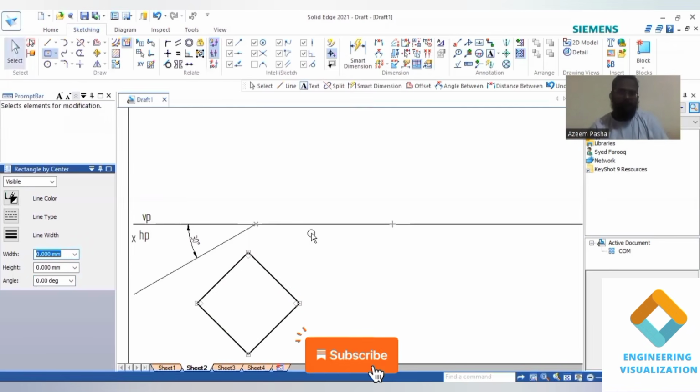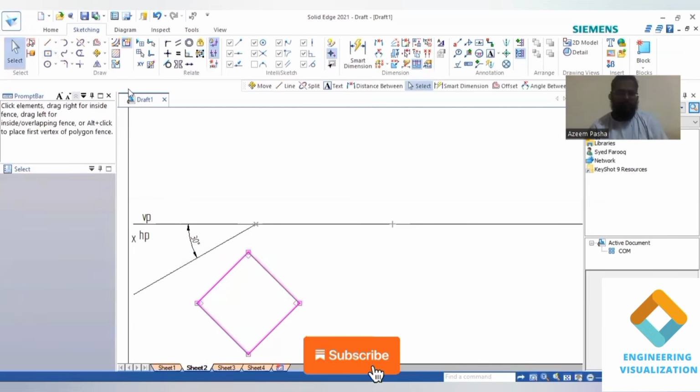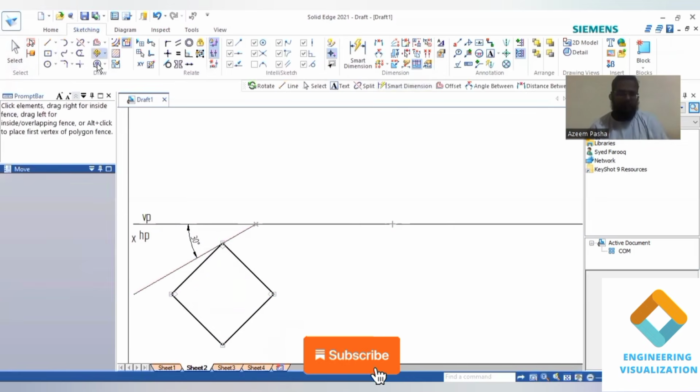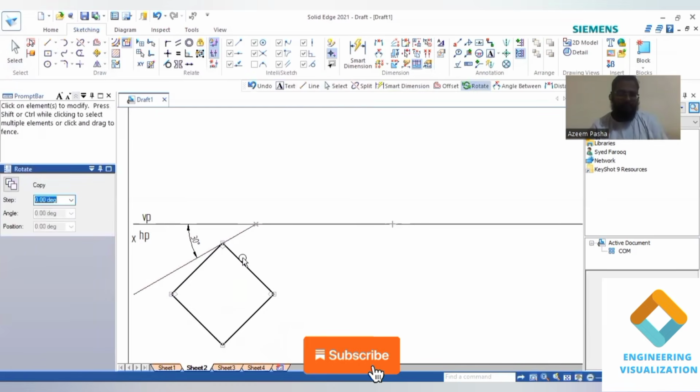When we place it on this 30-degree angle point, we select this, go to the move command, select the end point here, and place it on this angle line. Then go to rotate, and again select this whole thing, because this entire thing you have to place. Select the end point from one end to another end, and then place it on the angle line.